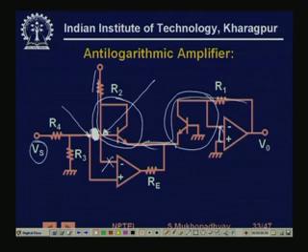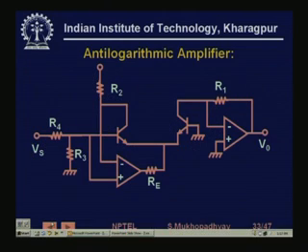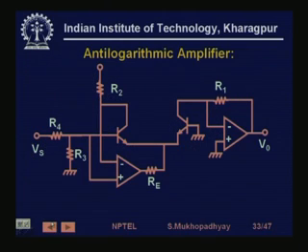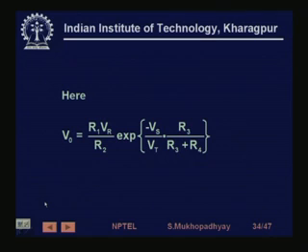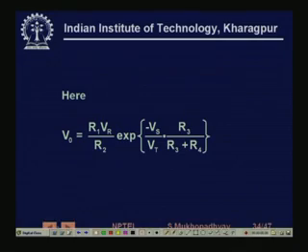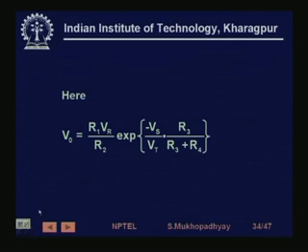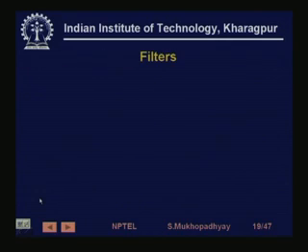So using these principles, if you write the equations, you can find out that the opposite effect can be achieved, and the output voltage in this case becomes exponential of Vs, so it is an anti-log operation. Okay.